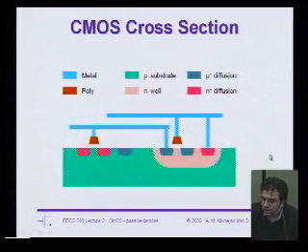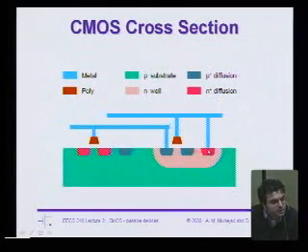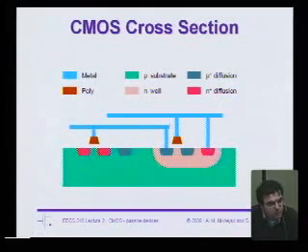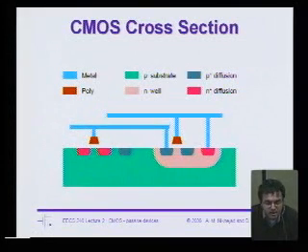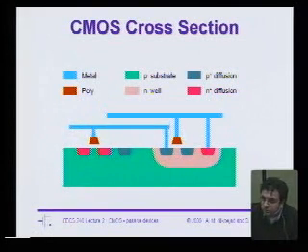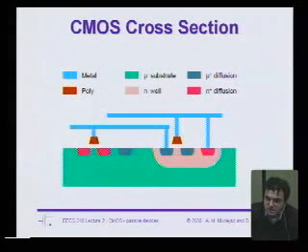Okay. On the other hand, your PFETs, you have the option. You can tie the body voltage really anywhere you like, as long as you keep the well junction reverse biased. And so typically you would tie it to the highest voltage available. But you can also just tie it to the source of the device and eliminate the body effect.